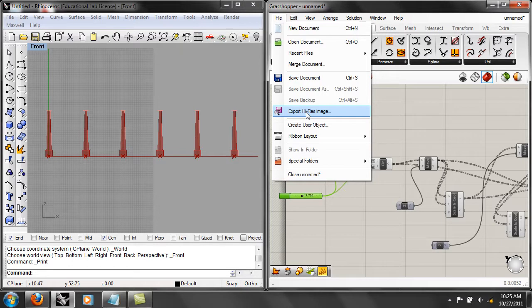Okay? So when you save, just saving it, yeah. You have to save the Grasshopper version and a Rhino version, or? If you have a referenced thing, you need to save that Rhino file. That line that you drew will be in a file. And then the Grasshopper script will use that Rhino file. So yeah, you need the script and the Rhino file. That's a great question. Yeah, if you use any Rhino geometry, you need that Rhino file, so that 3D file.